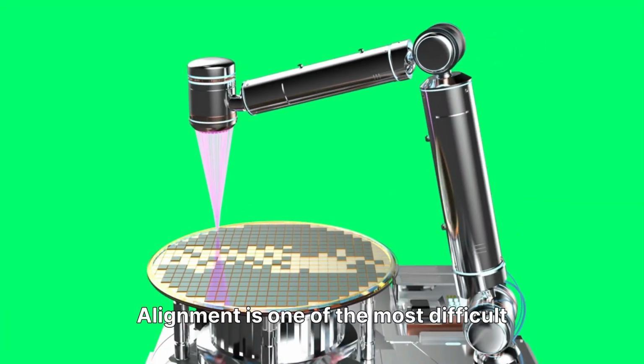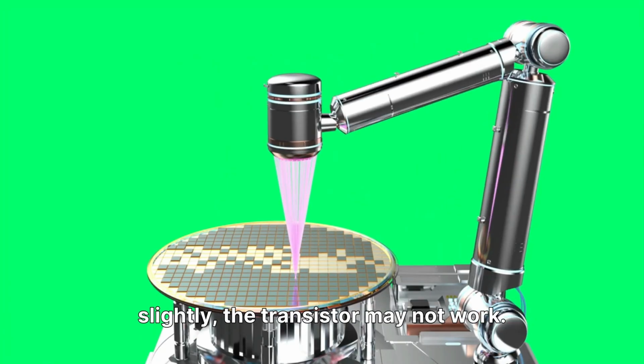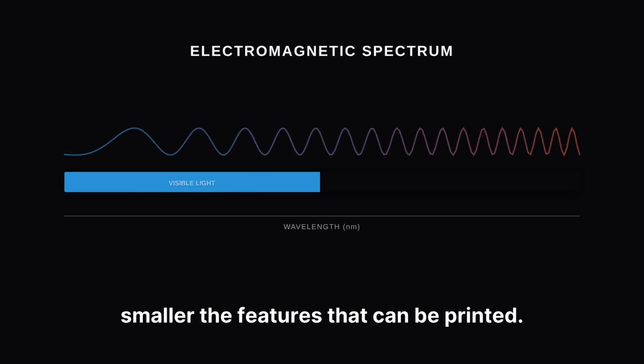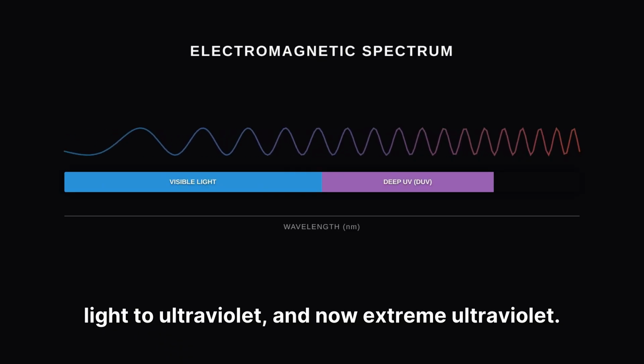Alignment is one of the most difficult tasks. If the new layer is shifted even slightly, the transistor may not work. In advanced chips, accuracy is measured in nanometers. The smaller the wavelength of light, the smaller the features that can be printed. This is why we moved from visible light to ultraviolet, and now extreme ultraviolet.